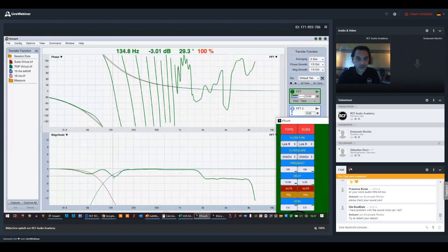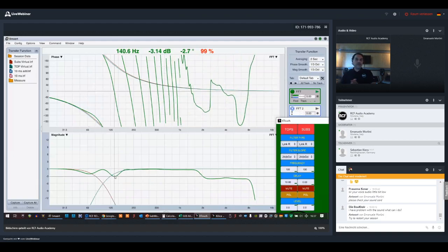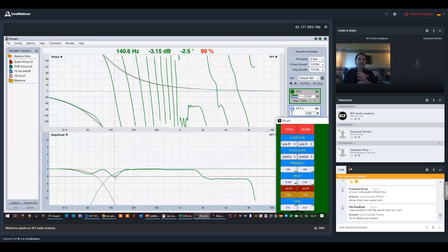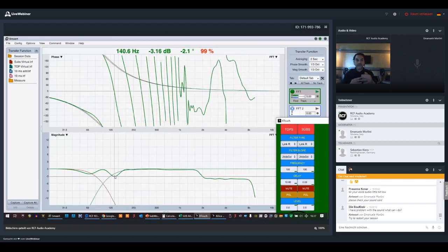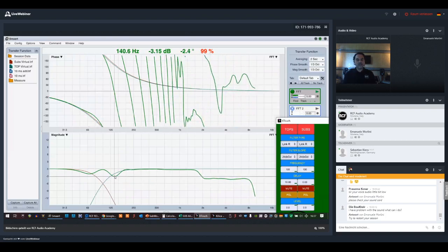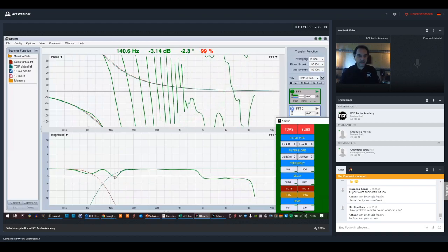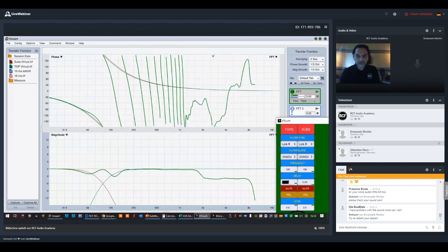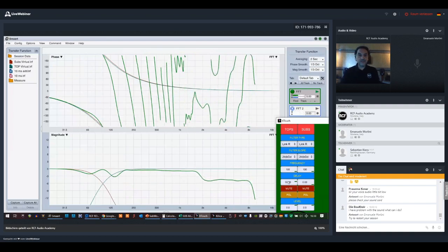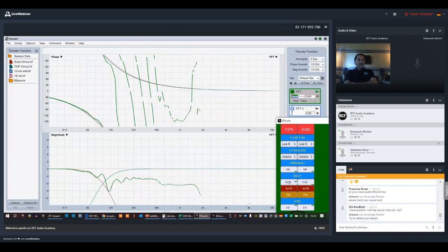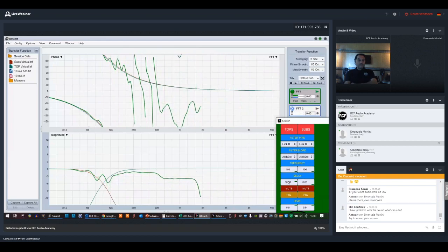In the surrounding frequencies, we start having cancellation because the phase, as the frequency increases, is rotating more quickly, creating differences between the reference and measured signal. This will cause cancellation both in the virtual domain as we are now, as well as in the real domain as we will be in a few minutes. If I increase, for example, by 3 cycles, by applying 30 milliseconds of delay to my tops, you can see that the cancellation will increase a lot.